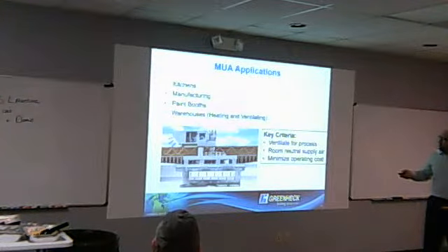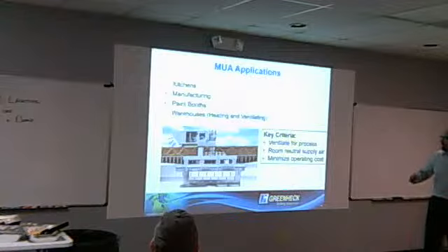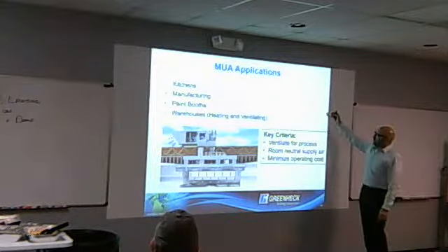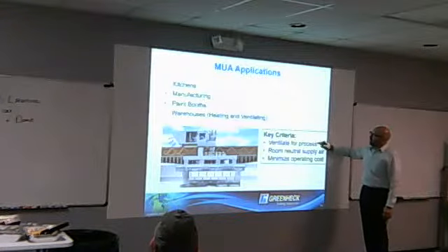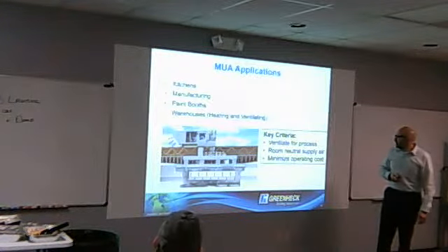In terms of this, it goes back to makeup air, we already talked about it. Kitchens, manufacturing, paint booths, warehouses, ventilating for a process. So DOAS for occupancy, makeup air for process.